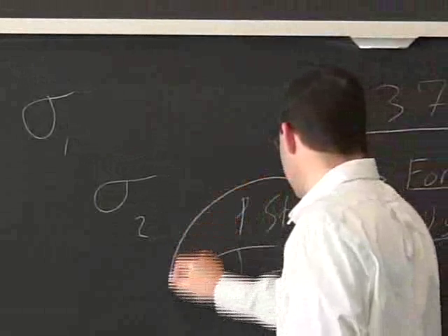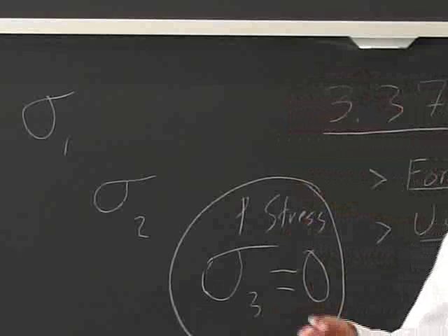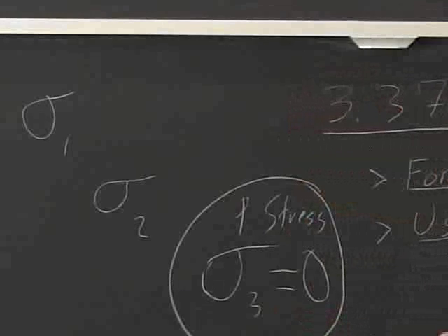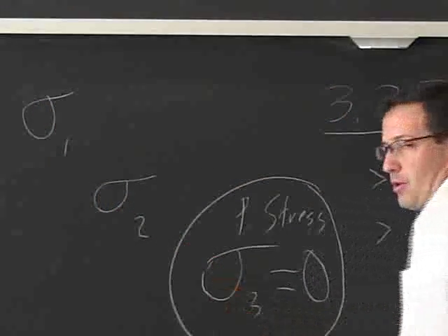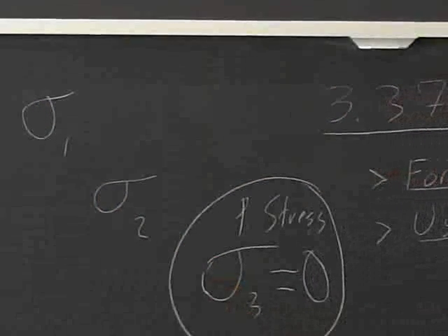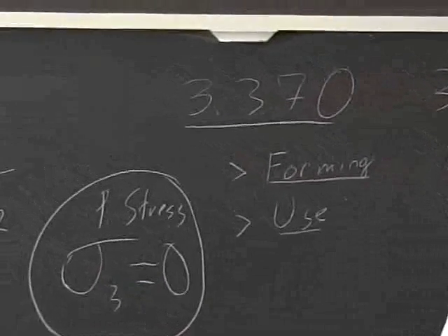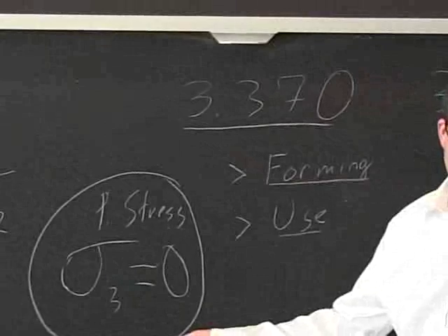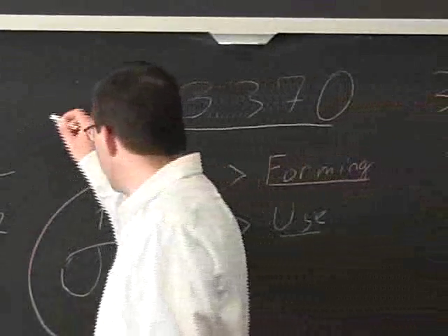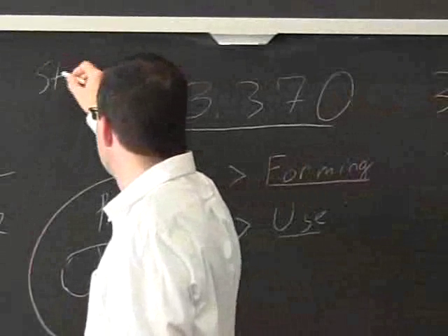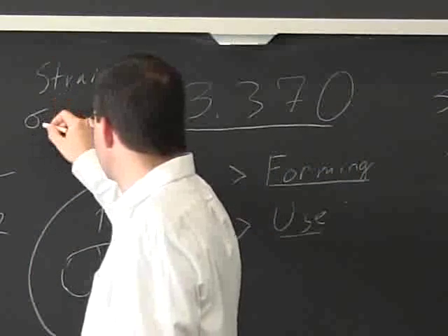And that is what makes this condition yield you a much bigger plastic zone than if you have stresses that are in tension in all three principal directions. And that's what we're looking at on the screen. So the top is, we have a 0, and the bottom is, I would say for plane strain, we may have the sigma 2 and 3 being similar.